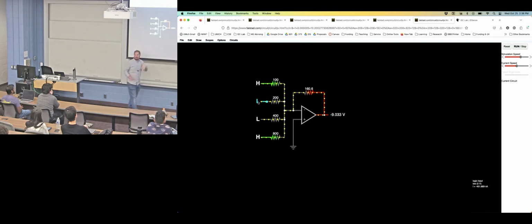If they're all the same resistor value, then they're all going to be skewed in the same way, right? With the ladder scenario, all those resistors were the same. So if you wanted 1 kilo ohm and you actually got 900 ohms, it's okay. The proportional steps are all the same. Here, it might not be okay. So you're susceptible to more error in these sorts of things.